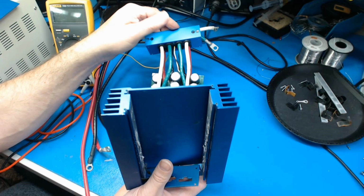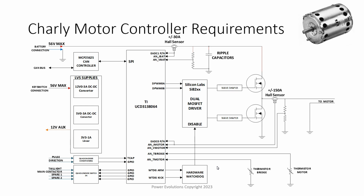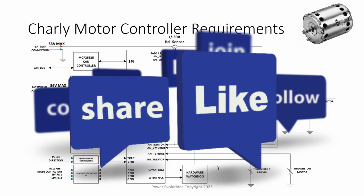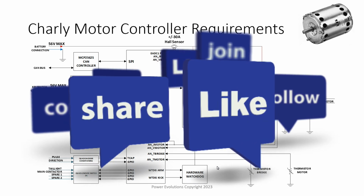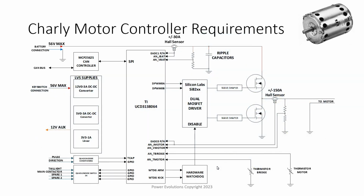My guess is it's probably 2 FETs for the top switch and 2 FETs for the bottom. So that doesn't really require a lot of heatsink space. It does, however, if it's switching inefficiently. And that is going to be dealt with during the tuning process, and also the layout. Hopefully we'll have a clean layout that keeps the loop areas small, so that we can keep the turn-on and turn-off times quick. So that's it for now, and in the near future I will do an update on where we're at with the main controller.